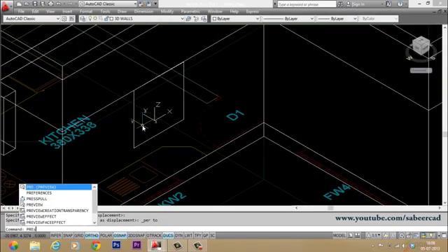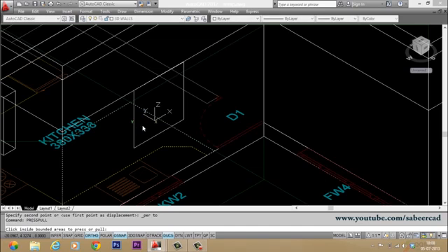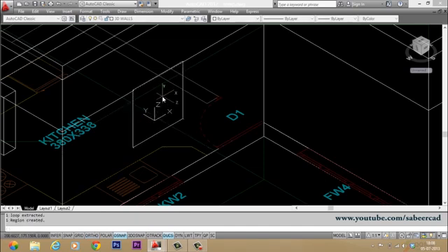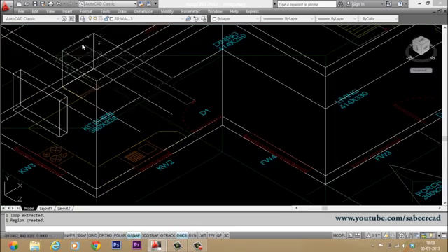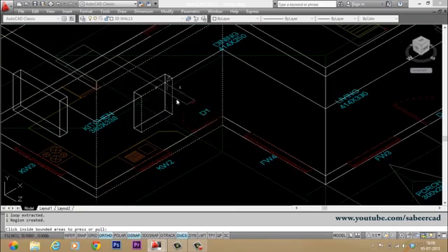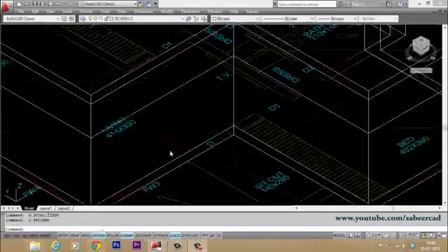Now you can give the press pull command. Type press. Just give an enter. Now you select the profile. Just click a point inside the profile. Then you drag to create a surface. Now you have pulled a surface and now you have made a cutout there.